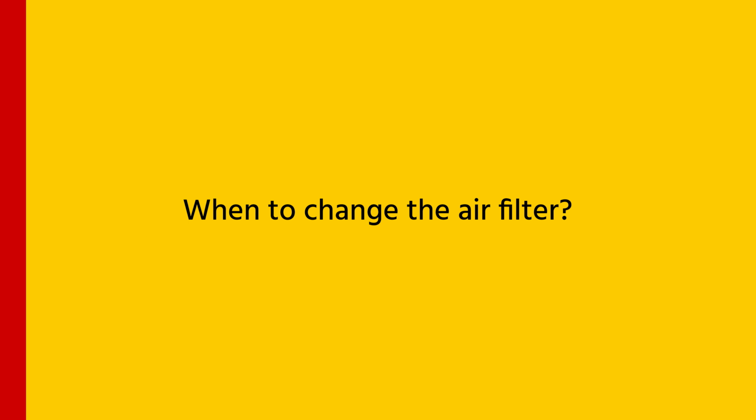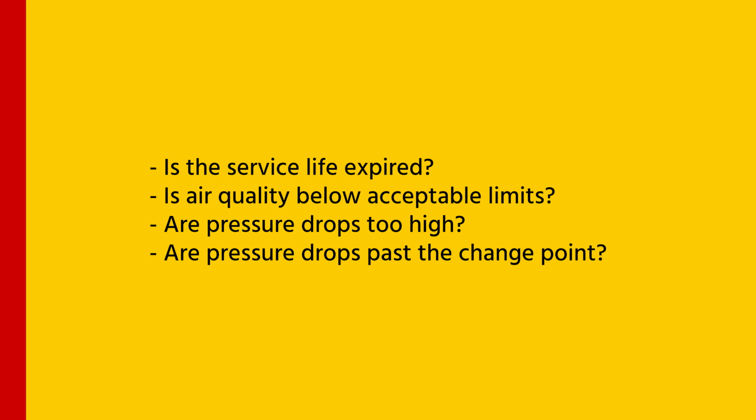So when do you change your air filter? Consider these 4 questions. Is the manufacturer's service life expired? Has an air audit revealed that the air quality is below acceptable limits? Are pressure drops exceeding acceptable levels? Are pressure drops exceeding the manufacturer's change points?